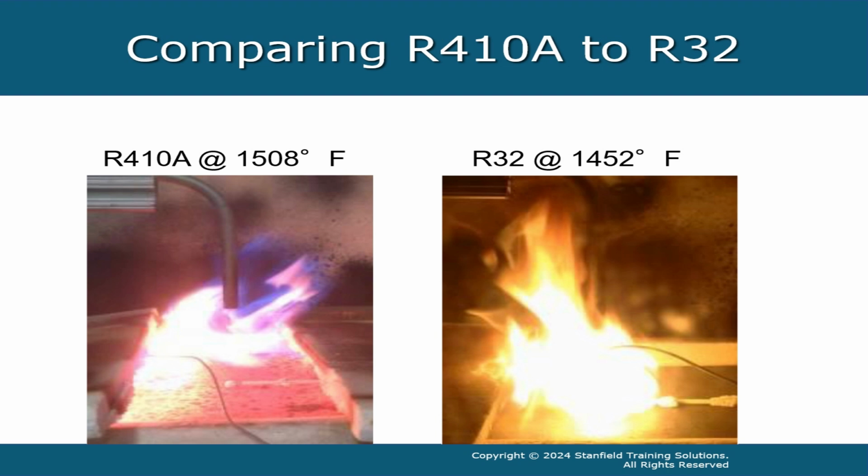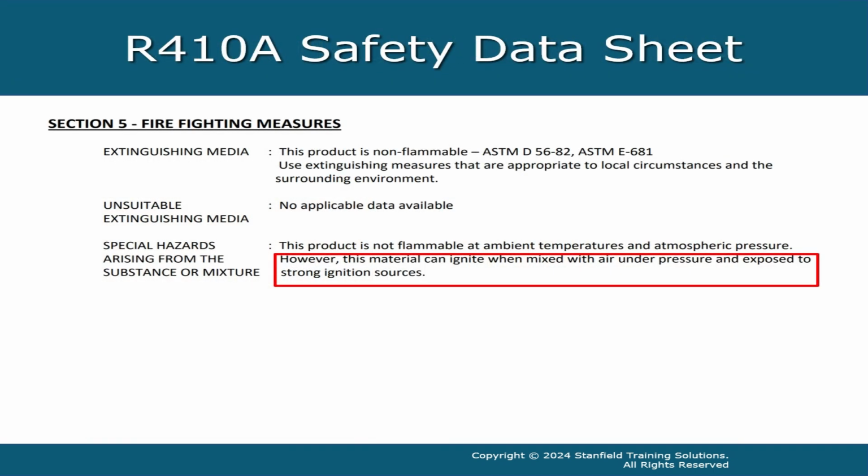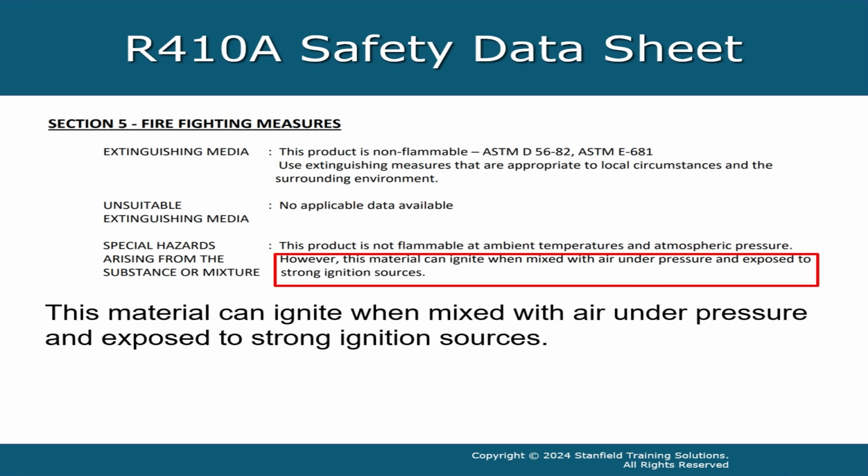Note that both of these pictures are of pure refrigerant, not refrigerant and oil. In fact, the safety data sheet for R410A tells us this material can ignite when mixed with air under pressure and exposed to strong ignition sources.